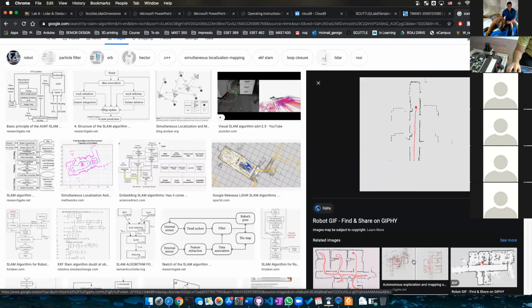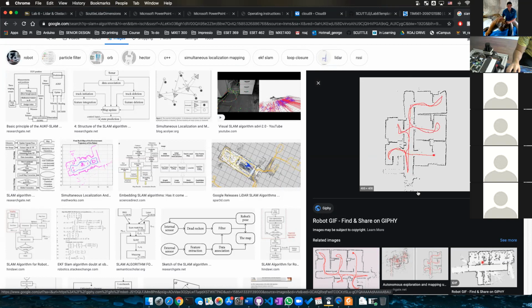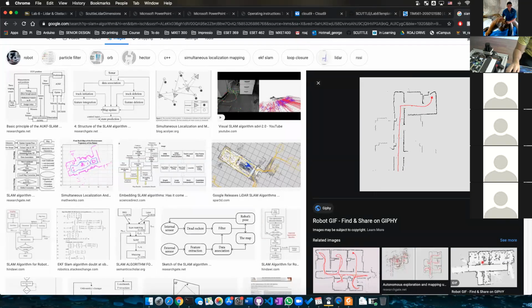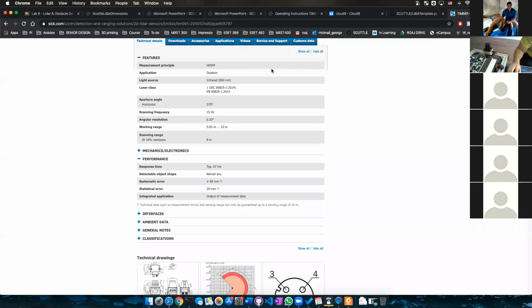This is what I was talking about. If you imagine your LiDAR as a point source of light, like a light bulb in the center of a room, everywhere there are shadows are places that you cannot see. As you move that light around the room, those areas that were initially in shadow would now be lit up. Similarly with the LiDAR, those are areas of the room that you would now be able to get data back for. Okay, so that's how you will map a room.